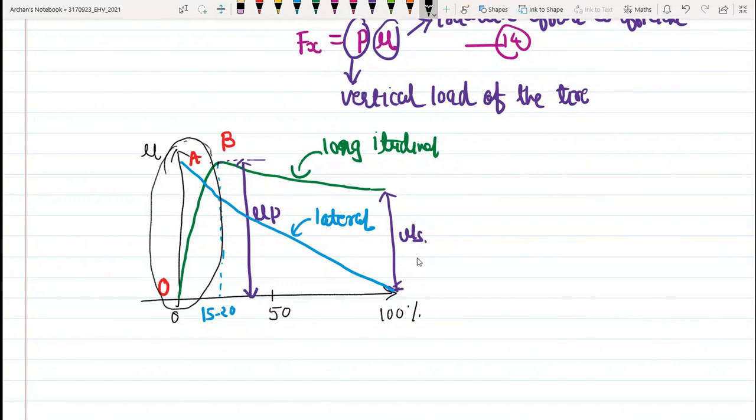So for normal driving, the slip of the tire must be limited to a range of 15 to 20%. We have the peak values of adhesion and sliding values of adhesion for different types of roads. We need to take care of the particular road and act correspondingly. Suppose I am talking about a concrete road.